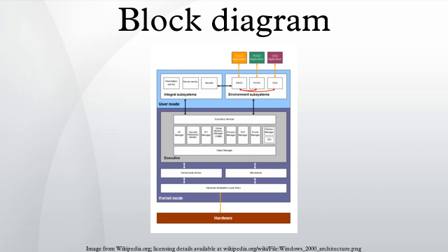Usage: as an example, a block diagram of a radio is not expected to show each and every wire and dial and switch, but the schematic diagram is. The schematic diagram of a radio does not show the width of each wire in the printed circuit board, but the layout diagram does. To make an analogy to the map-making world, a block diagram is similar to a highway map of an entire nation.